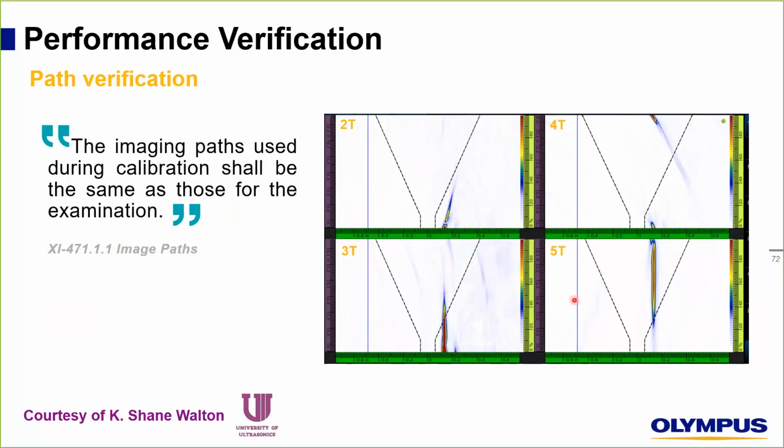Imagine if you don't have 4 groups in your machine and you want to do the inspection. If you have just one group, you have to run the scan or the weld 4 times, because to prove that you detect the full extent of the slot, you use 4 runs as well. So this is very important.